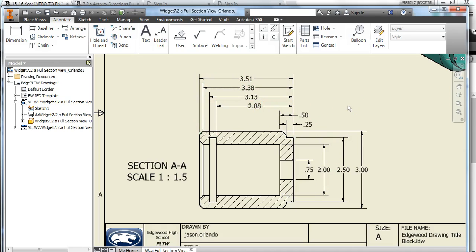The last step, and this is basically the end of it, is we had talked about last week that within ANSI standards, there are different choices and formats. Just because we are working within a group of standards doesn't mean there's always exactly one way to do it. Sometimes it's just personal preference. And these dimensions right here that are vertical dimensions, the text is horizontal, which is nice because it's parallel to these and easy to read from one side.